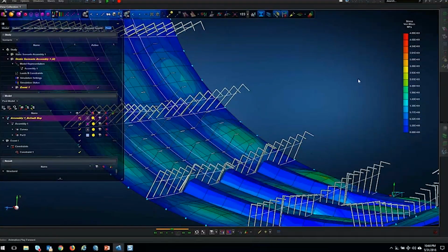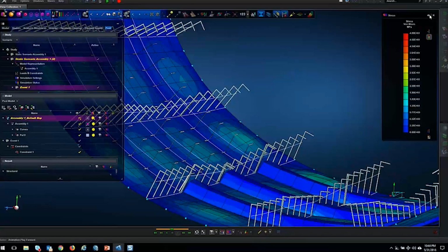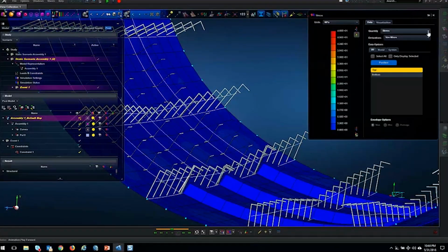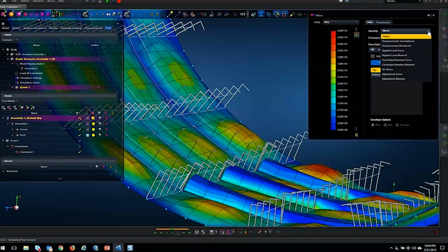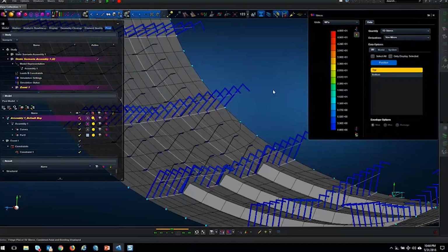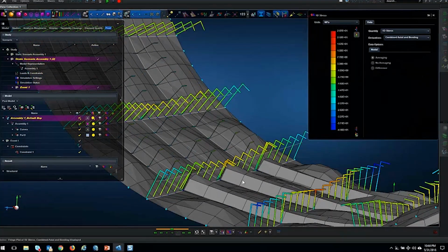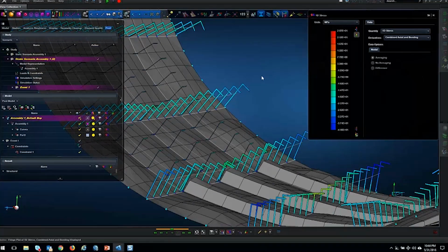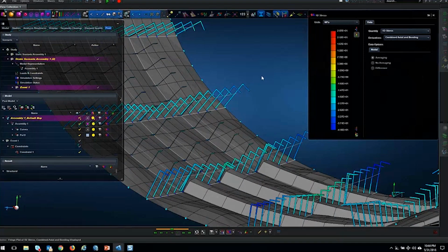And even if you would like to look at the stresses or the displacements in the beam element itself, you can go to only the 1D beam element. You can toggle that to look at the display along the cross section of those beams. In this case, I plotted just the stress. Stress may not be relevant.